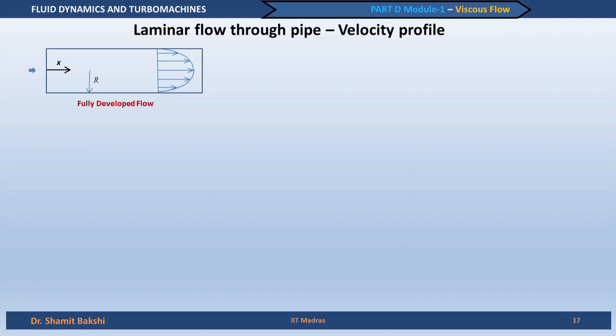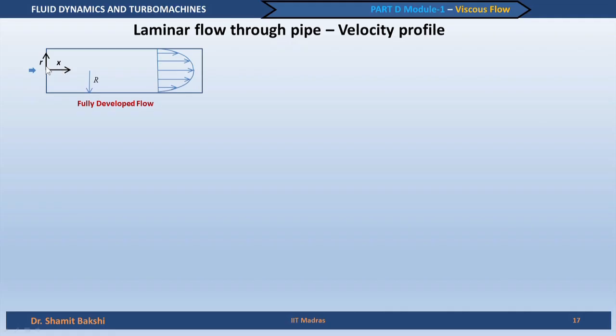For a circular cross section pipe, it exactly represents the geometry of the object. So, this is always better, because in fact when we deal with a sphere, it is better to use a spherical coordinate system. So, we use the x-r coordinate system rather than the x-y coordinate system which we have dealt with so far. The x-y coordinate system is basically Cartesian. This is a cylindrical coordinate system, and the velocity in the x direction is u, and that in the r direction is given as Vr.